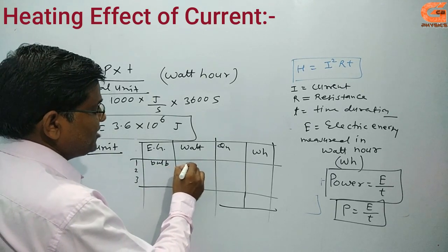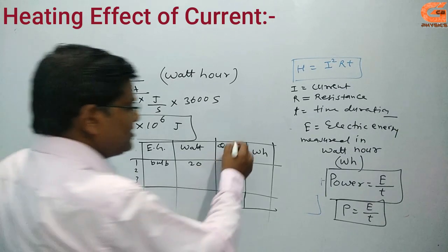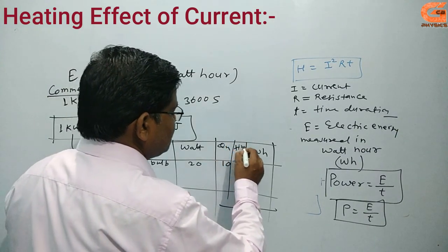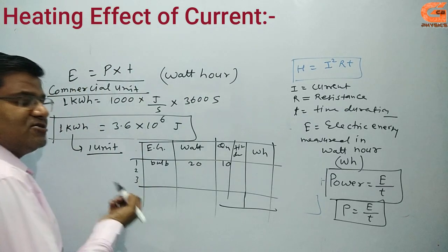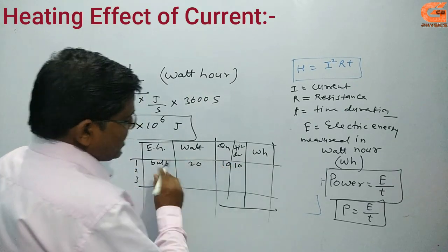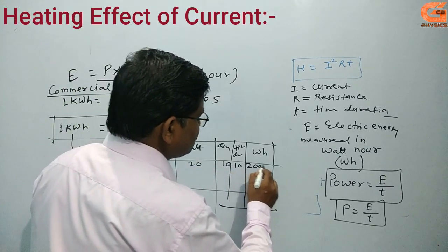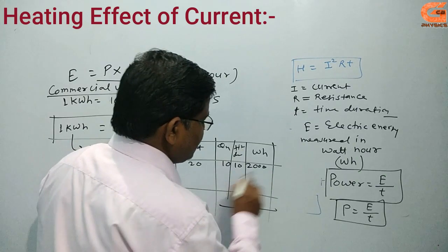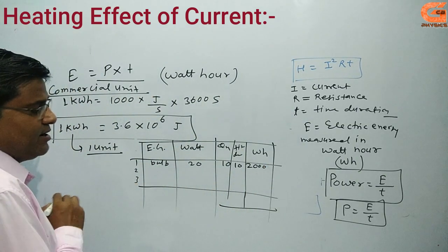Just like the bulb: suppose 20 watt, quantity approximately 10. And one more thing is time duration, how many hours they are glowing, say 10. You multiply all these, and it becomes 2000 watt hour in a day.